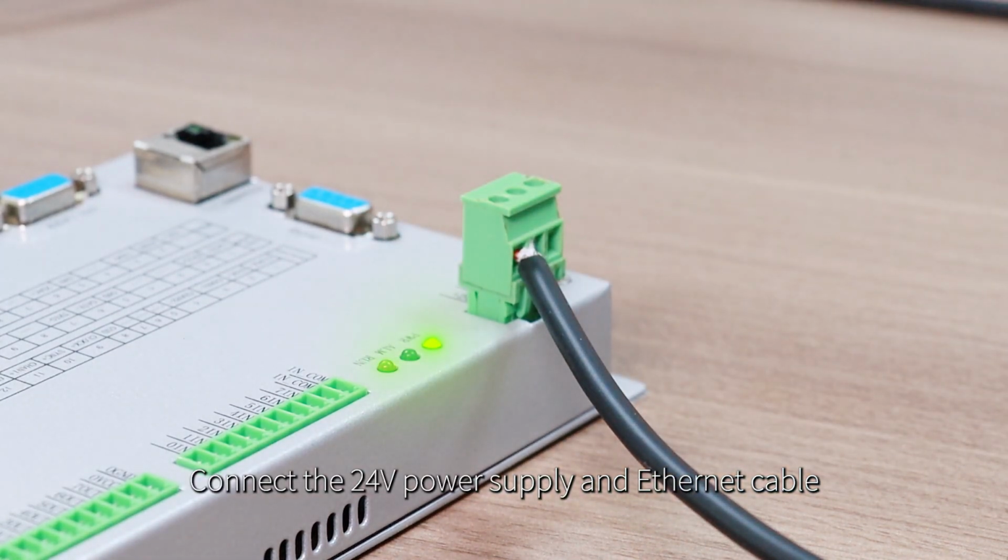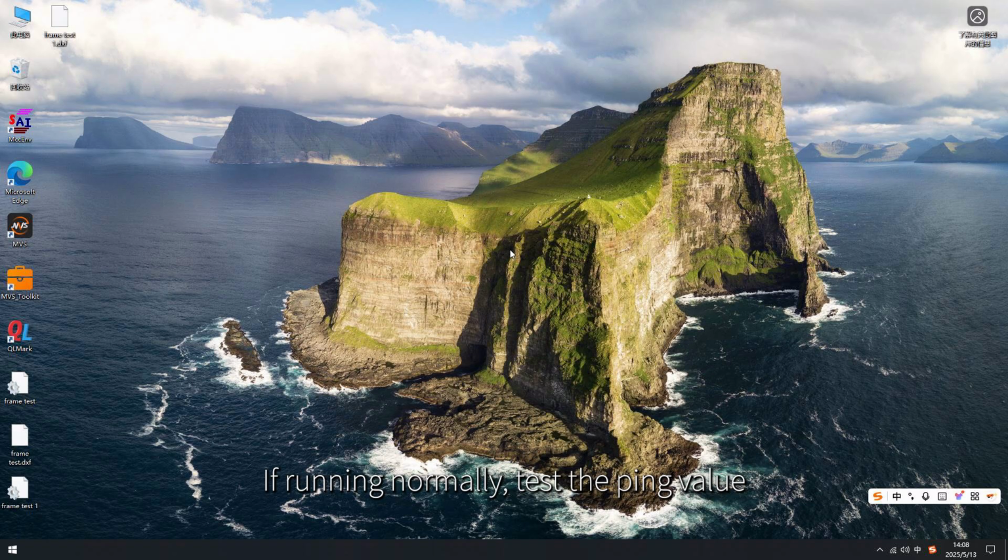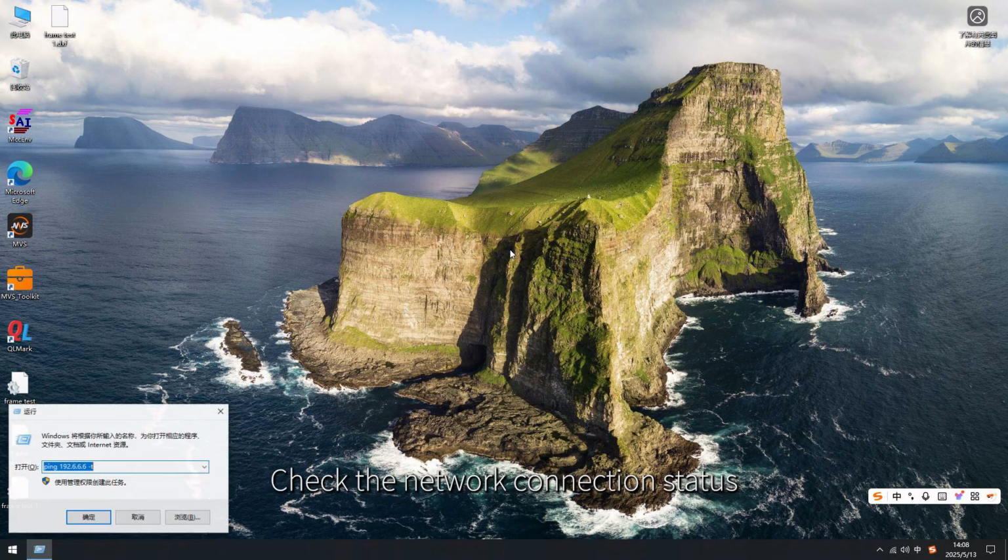Connect the 24 volts power supply and Ethernet cable. Check the operating status of the board's indicator lights. If running normally, test the ping value. Check the network connection status.